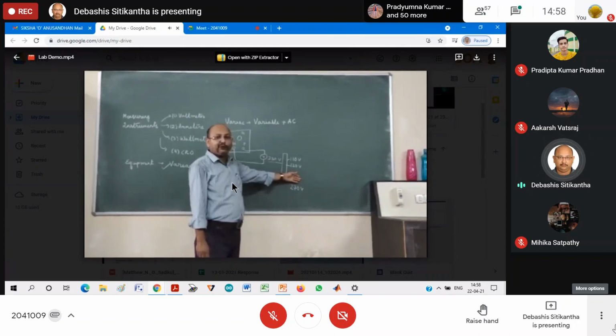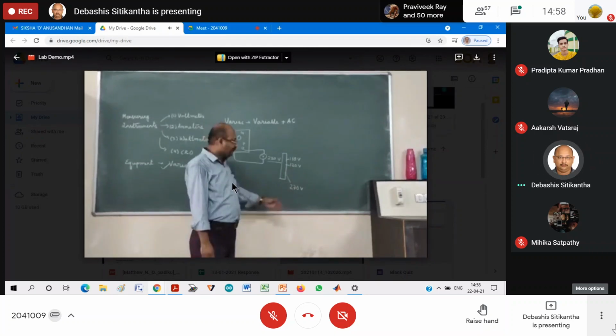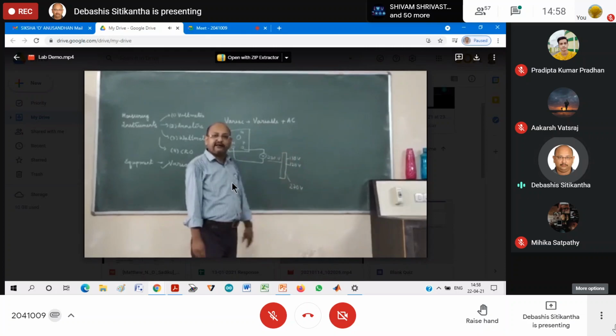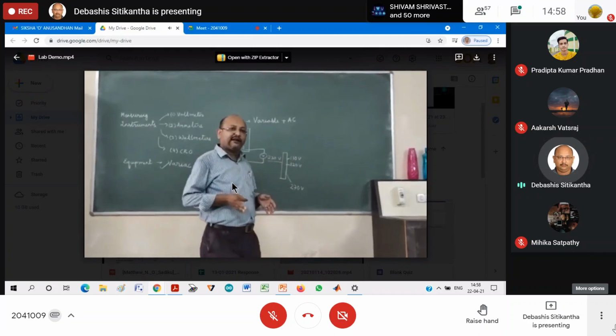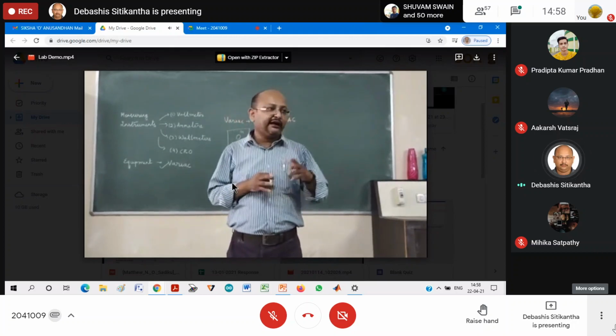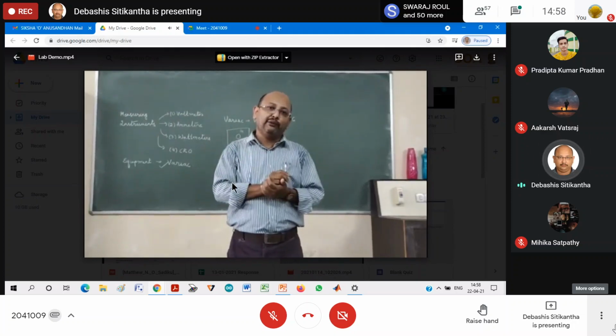Over here, there is no change in the voltage level. Similarly, if I want, I can also step up the voltage from 230 volt to 240 volt, 250 volt, 260 volt, or 270 volts. So a variac is basically going to give a voltage of my choice. I can obtain any voltage from 0 to 270 volt out of this 230 volt input.